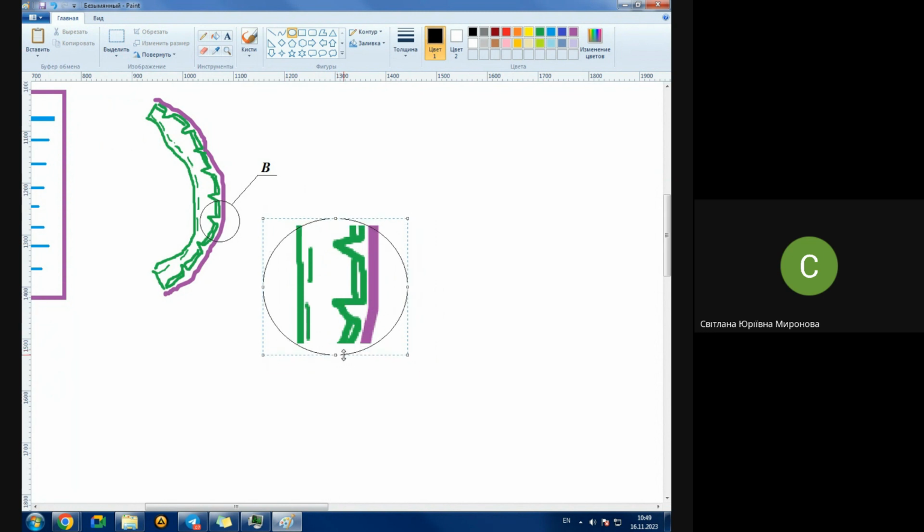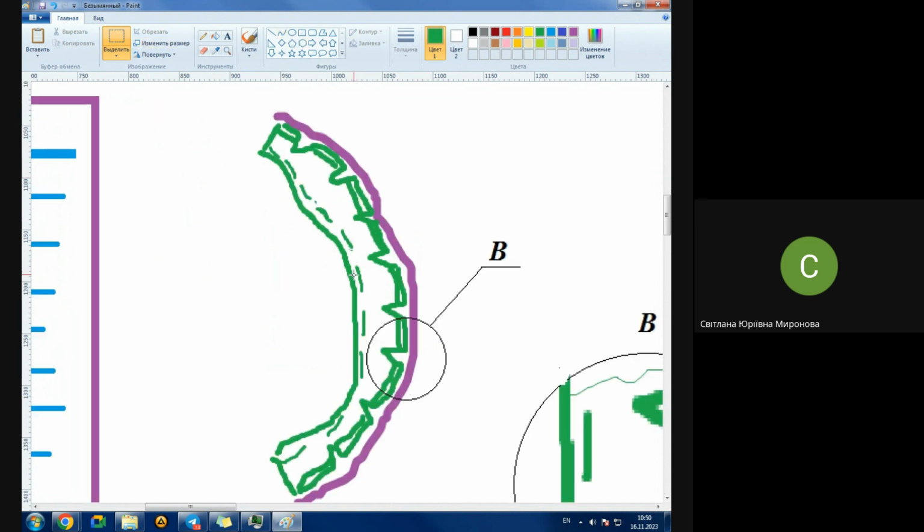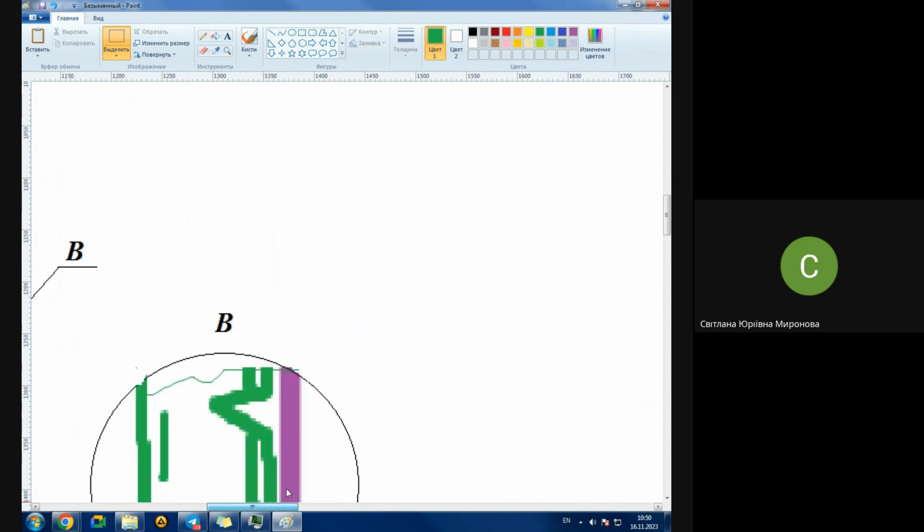It's also not compulsory in your case to draw those circular lines according to modern rules. You don't need to draw a circular line. You just show here it is a cross section, which is torn off. Let's say a thin line, a very thin line, and something like, yeah, it's finished. It's broken, and that is view B. What is it for? To show bases and to show some place with a stringer, because in that little picture I'm already not able to show it.